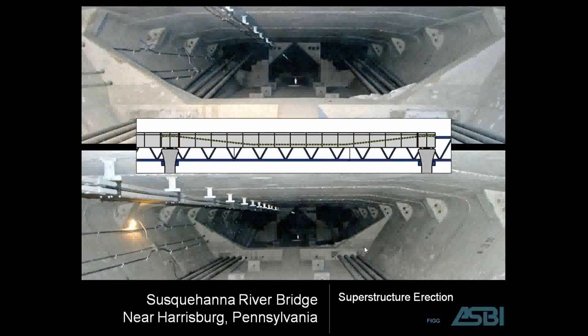Here we have the interior of the box, and I can show you the locations of the temporary post-tensioning. Up on the upper right, you see the blister on the inside of the box with the 2 holes. Temporary PT, usually threaded bars, are applied through those. Also down here on the bottom, you can see some blisters on the bottom of the hole. That allows temporary post-tensioning to be applied there.